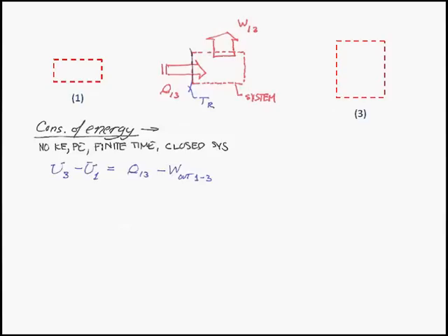All right, that is not equal to the useful work out. The conservation of energy accounts for all energy, not just the useful part. That'll change when we look at exergy, okay? But conservation of energy needs all of the work, not just the useful piece. So there's my conservation of energy equation. I put that in terms of little u and mass.